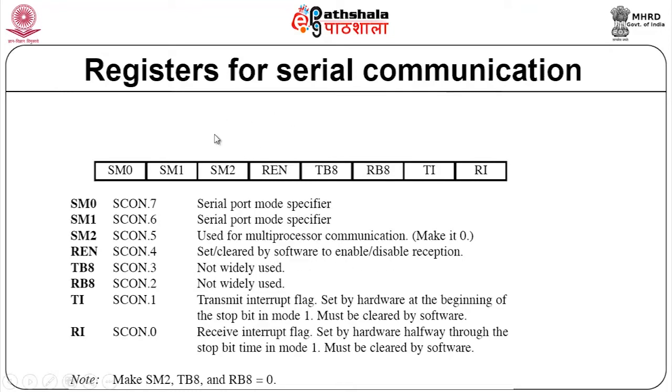Now the next important thing is your SCON register, which is nothing but the control register for serial communication. In 8051, this is the format of the SCON register which is used for serial communication. There I will have SM0, SM1 and SM2, and REN, TB8, RB8, RI and TI.